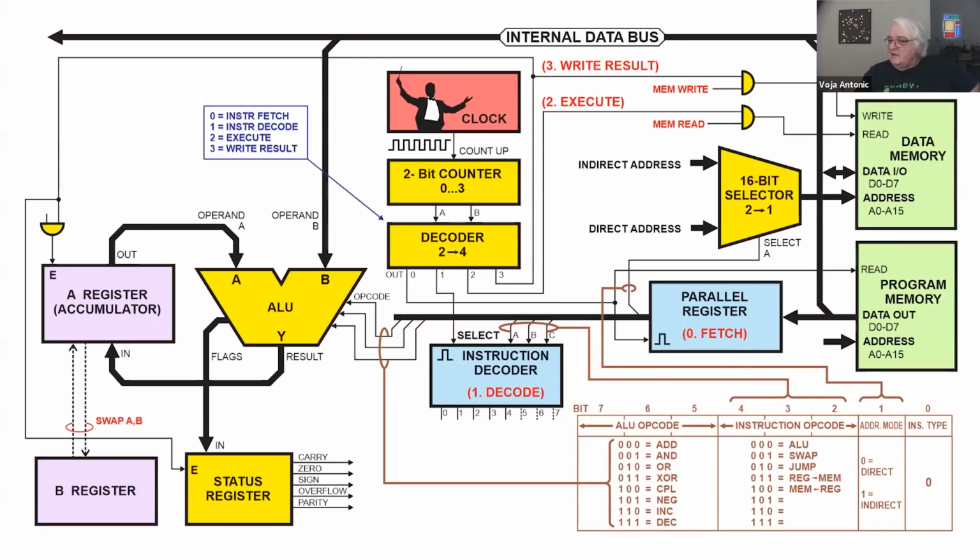The addresses are also mostly, this is a hypothetical 8-bit processor actually, and these addresses are 16-bit. It's not enough to have 8-bit addresses. And here in program memory, there are also 16-bit addresses. So we can address it directly from the program memory when we say, write this data to say address 0007. And then it's direct addressing.